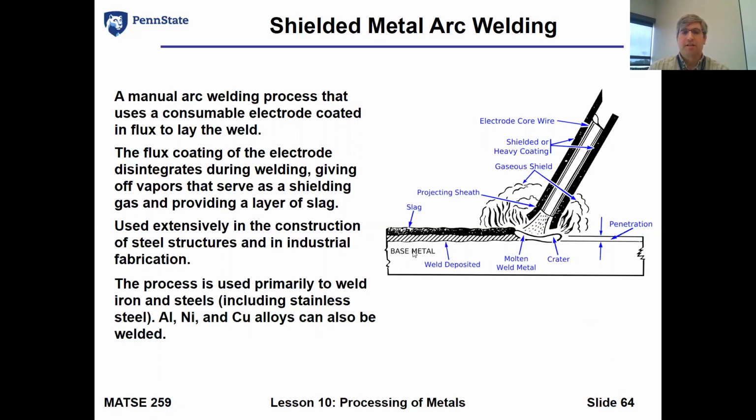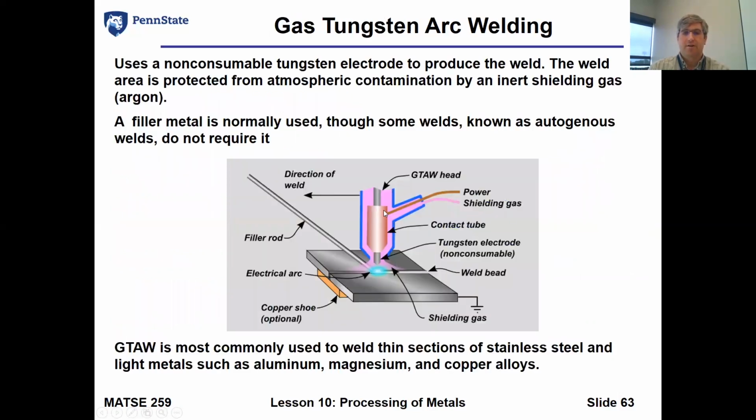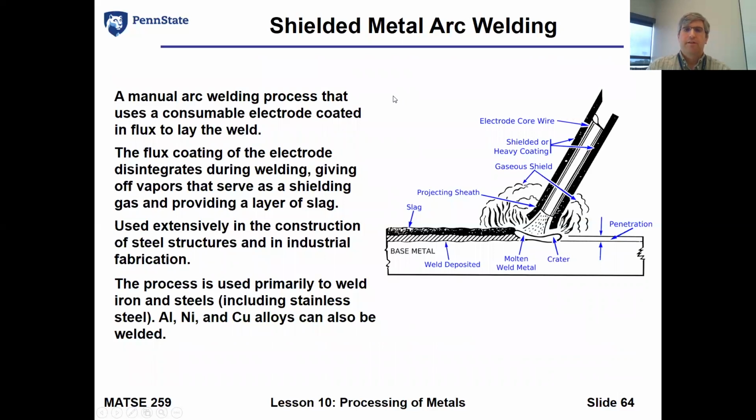Now, there's no shielding gas in this. In gas tungsten arc welding, we feed inert gases around the weld metal to keep it from oxidizing. Typically argon or some combination of argon and sometimes helium, depending on the level of heat transfer that you want in the weld. The shielded metal arc uses what is almost a flux on the outside of it.